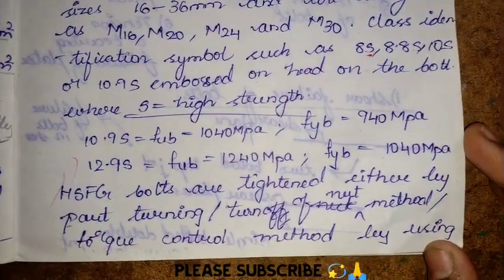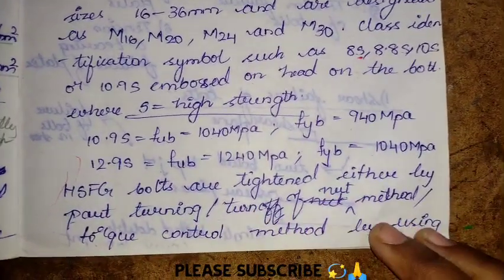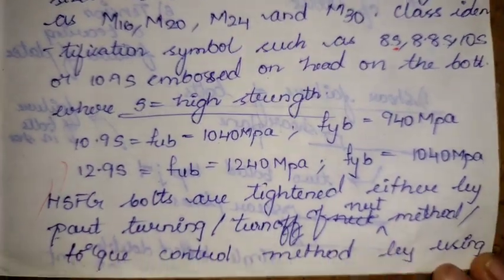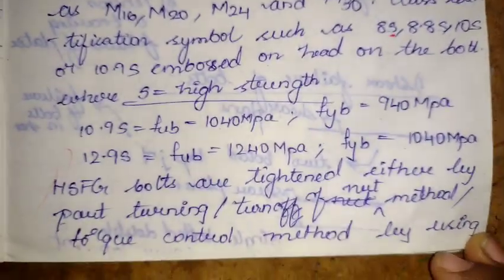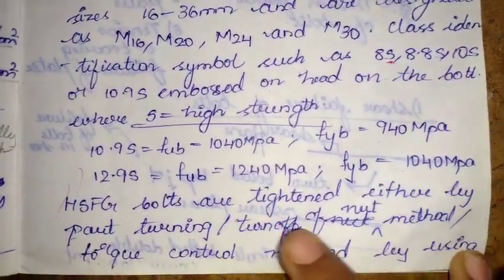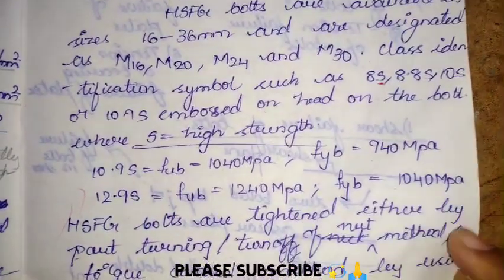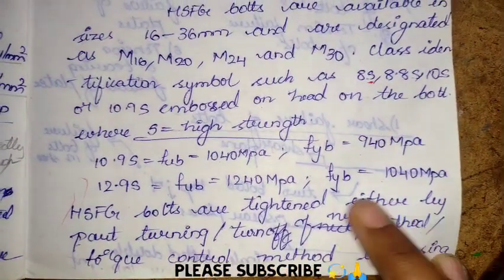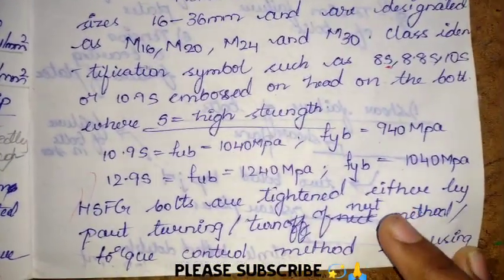These HSFG bolts are tightened either by the part turn or turn-of-nut method, or by the torque control method using load indicator washers. Depending on the requirement or the availability, we select one method to tighten these HSFG bolts. Just by using some wrench you cannot tighten this. We have methods, techniques and instruments to tighten the HSFG bolts, so depending on availability, we select one.